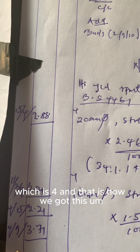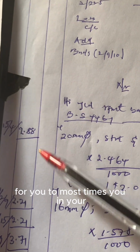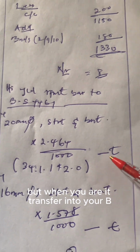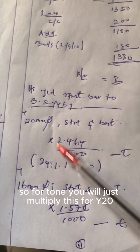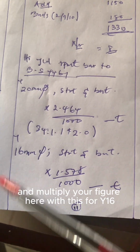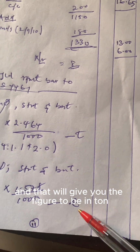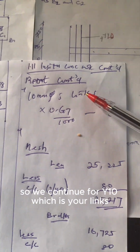And most times in your taking off, your quantity might be in meter, but when you are transferring to your bill, it can be in kg or in ton. So for ton, you will just multiply your figure here for Y20 and multiply your figure here for Y16, and that will give you the figure in tonnes. So we continue for Y10, which is your length.